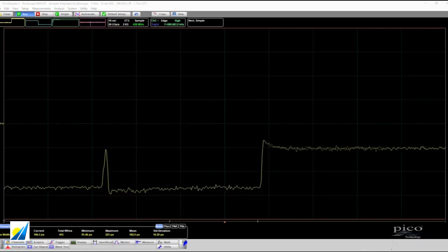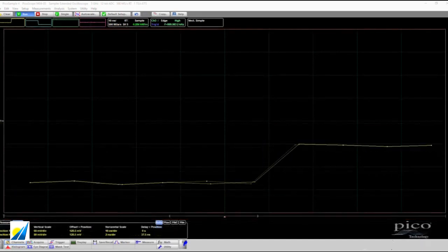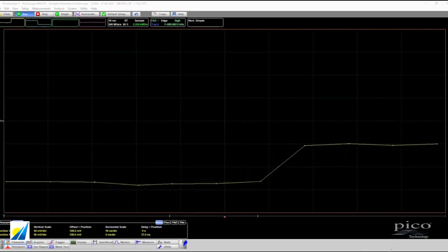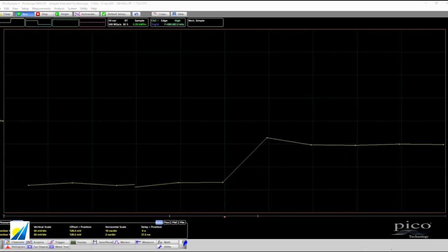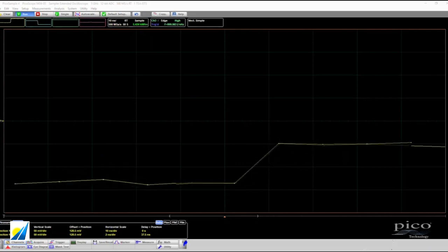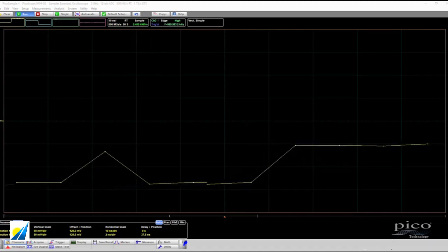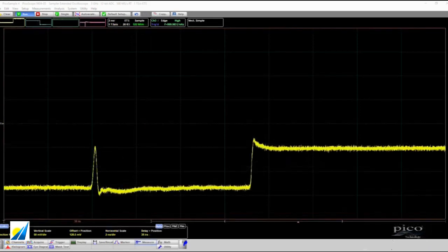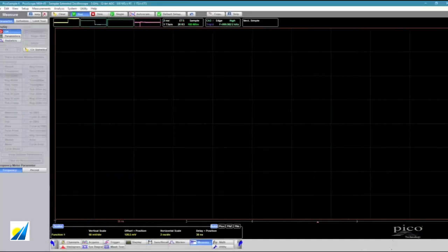Now in real-time mode, our sampler extended real-time oscilloscope will do a rather worse job. In this case we really don't have enough samples to capture that 150 picosecond pulse or data bit in single shot at all. We can capture slower transient events, but we will miss that 150 picosecond pulse. All broadband real-time oscilloscopes and the SX-RTO use random equivalent time sampling on repetitive waveforms or clock-related data eyes to increase the sampling density.